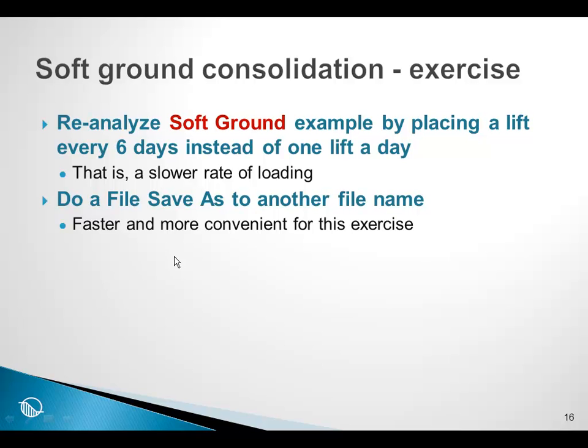Now, as a class exercise, I would suggest to you that you save this problem under a different name using File, Save As, and then repeat the analysis, but make the duration for each one of the fill, say 6 days, and then reanalyze the problem and take another look at the factor of safety.